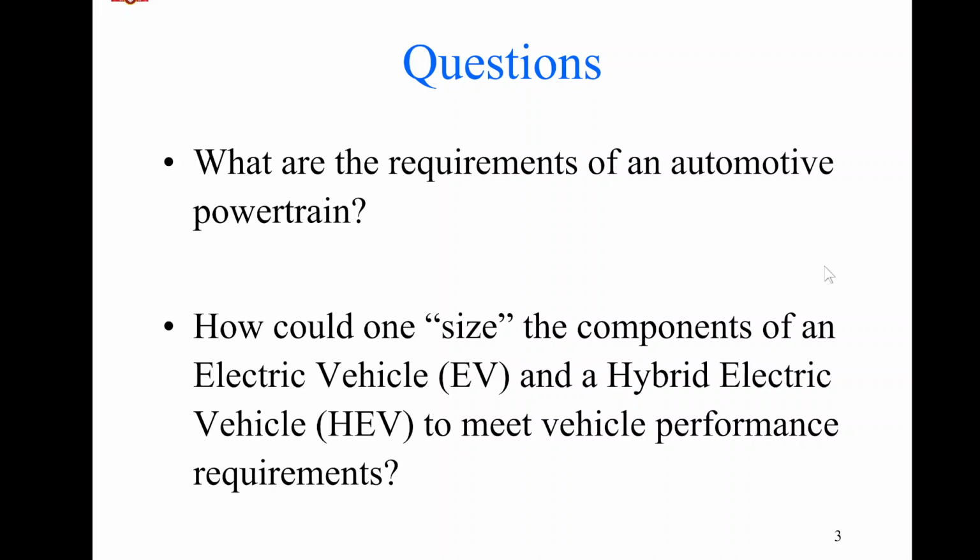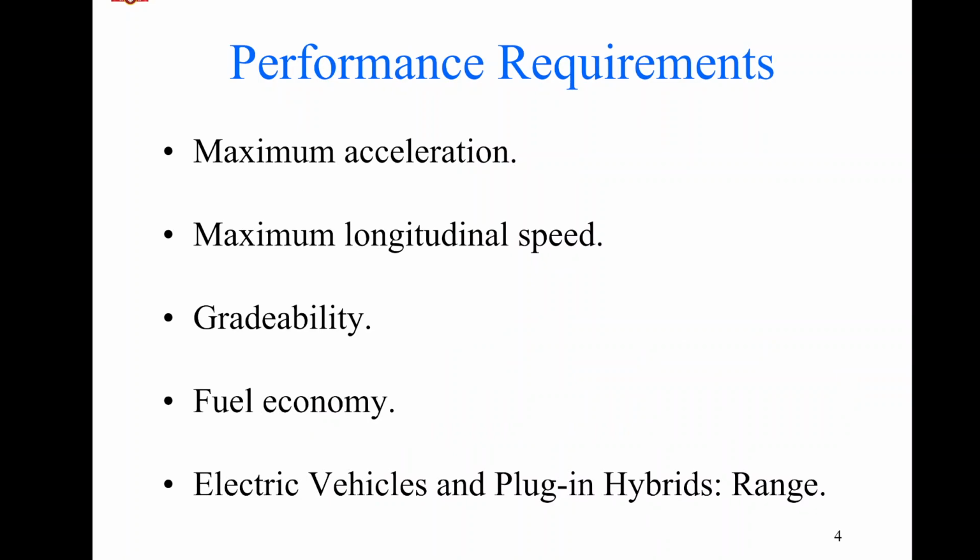We started our discussion on electric and hybrid electric vehicles with a few broad questions. First one being, what are the requirements of an automotive powertrain, and how could one size components of an electric vehicle and a hybrid electric vehicle to meet the vehicle performance requirements? Performance requirements were given in terms of maximum acceleration, maximum longitudinal speed, gradability, fuel economy, and for electric vehicles and plug-in hybrids, in terms of range.